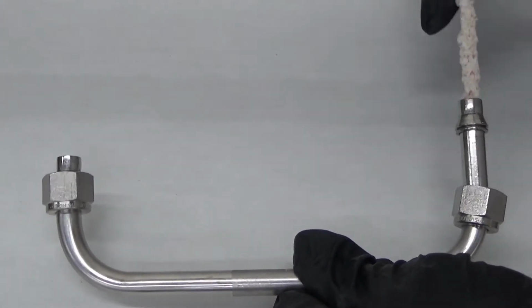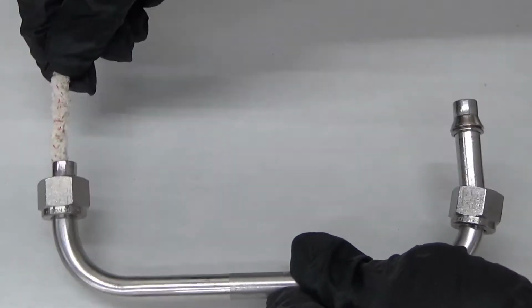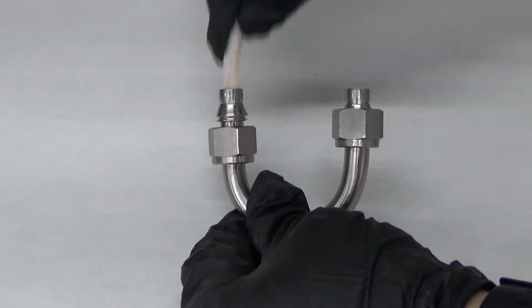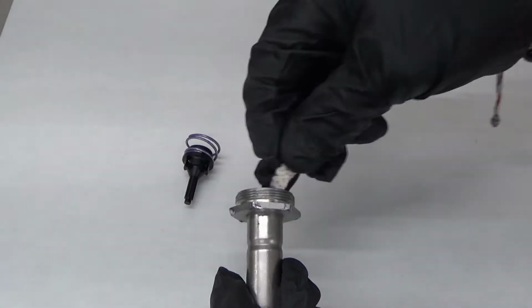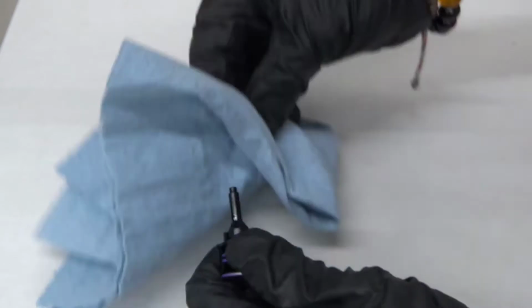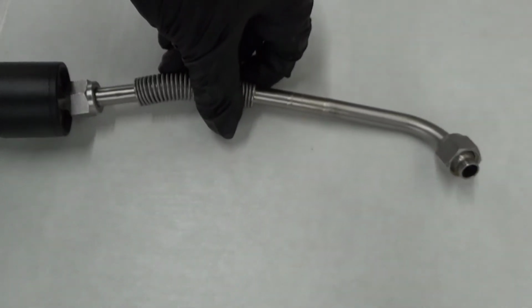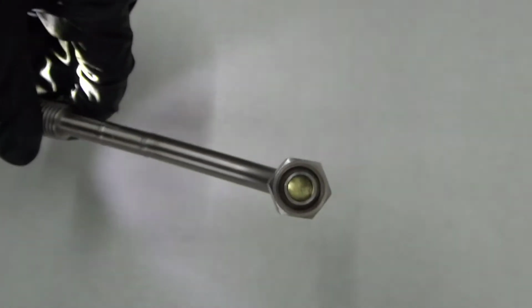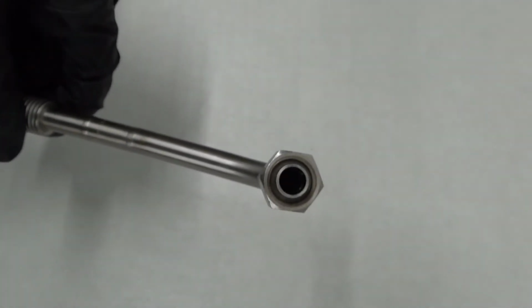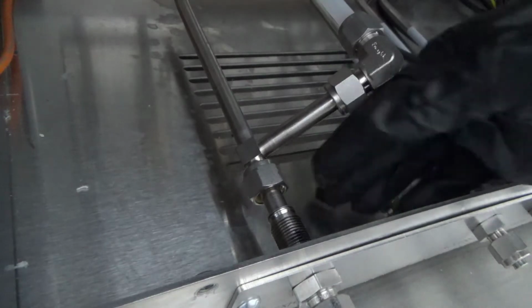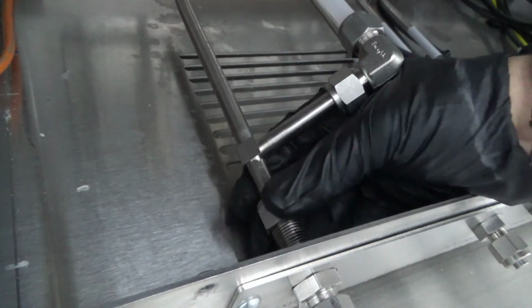We would then use our pipe cleaners to clean and clear all pipes that were removed. If necessary, you can drop these pipes in the wash for no more than 2 minutes. This may be necessary for components with sharp 90-degree angles. Again, we can use a flashlight to verify that the components are clean and clear of debris. Once all components are cleaned and dry, we can begin reassembly.